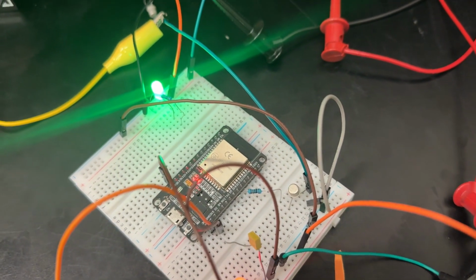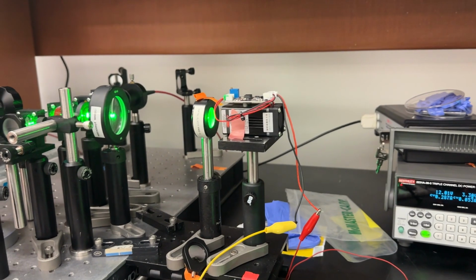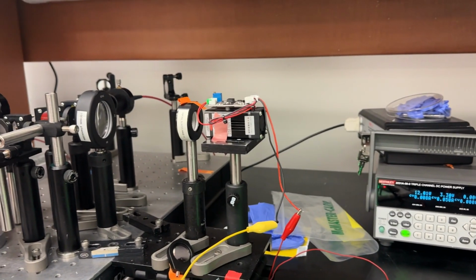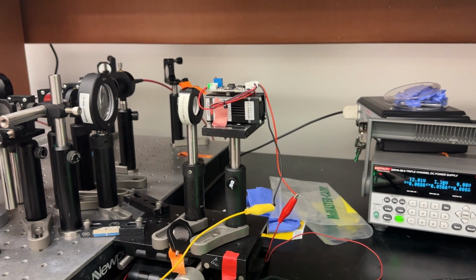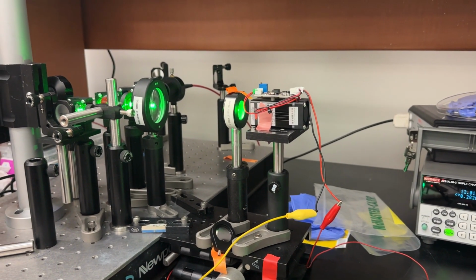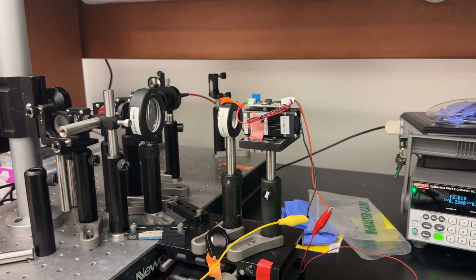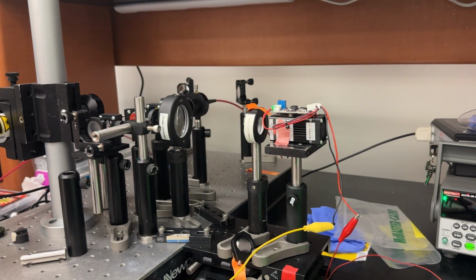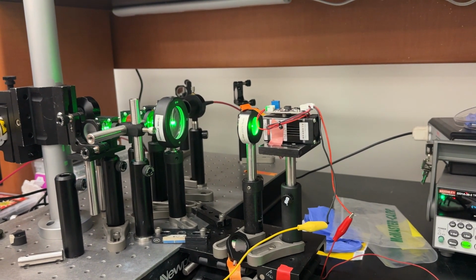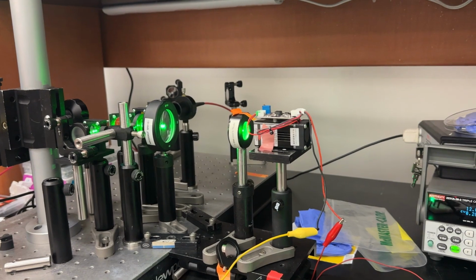The way we have it set up right now is the code is cycling on and off every 2 seconds, pulling the resistor high to low and interrupting the ground connection for the laser, which is turning it on and off. The next step would be to connect it to the Raspberry Pi alongside the LCD display. And instead of it cycling on and off, it would then be turning on and off via input on the LCD display.